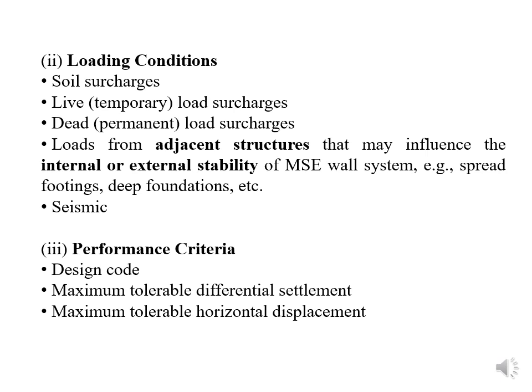Maximum tolerable horizontal displacement, because your structure may also face horizontal pressures, so that also you have to think before starting the design. Design life, what should be the life of your soil reinforced wall or mechanically stabilized earth wall? And construction constraints, what are the problems you are going to face at the time of construction? That also you have to think before starting the design.